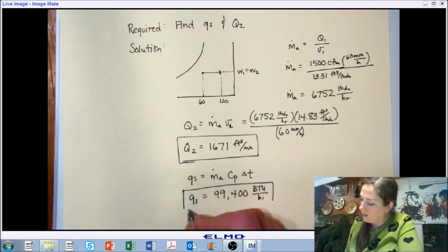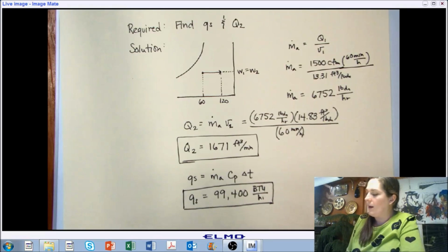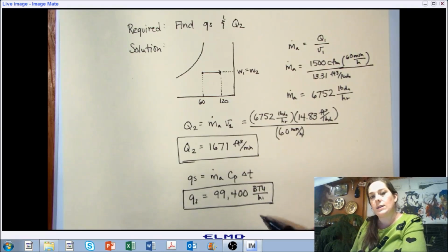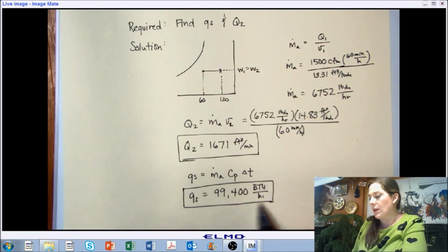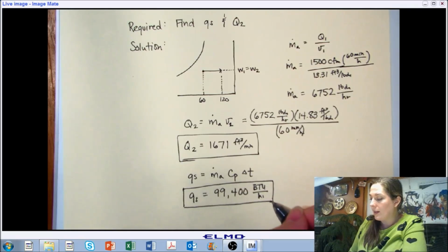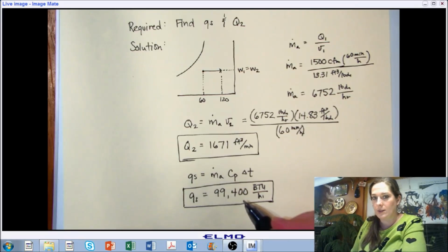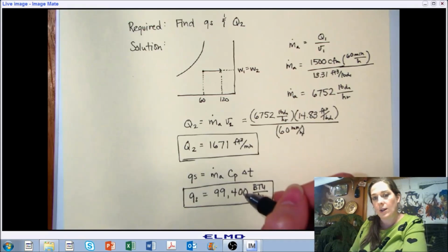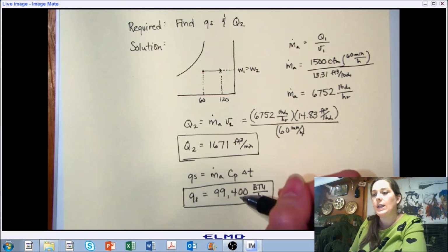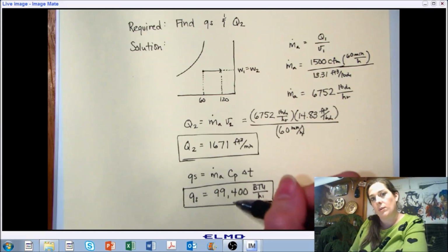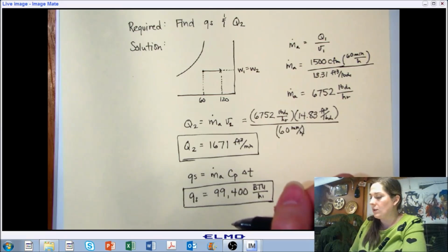It's important to also start to think now about, as we talk about the energy required, this is the amount of energy required to go from state point 1 to state point 2. In practicality, when you use a piece of equipment to get from that, there's also an efficiency on that piece of equipment. So this is the amount of actual energy required just for the process change, but when you apply a piece of equipment, you have to consider the efficiency of that piece of equipment. So the actual amount of energy needed is going to be greater than this, because some of the energy is lost due to the inefficiency of the equipment that's used.